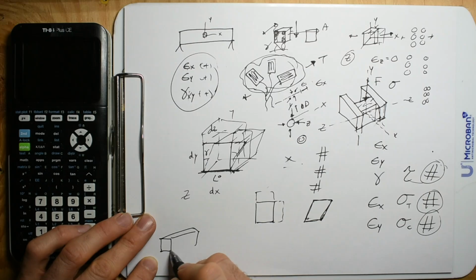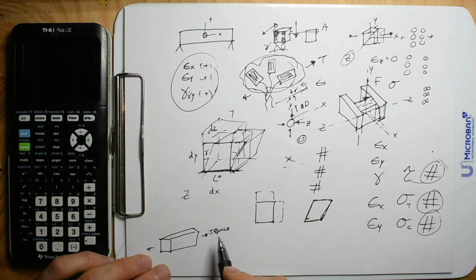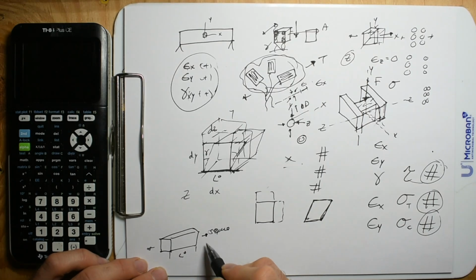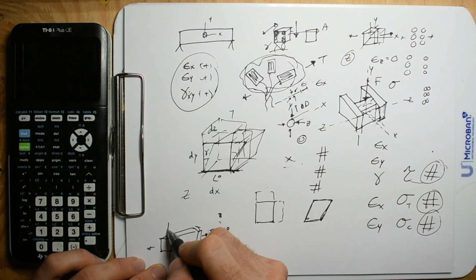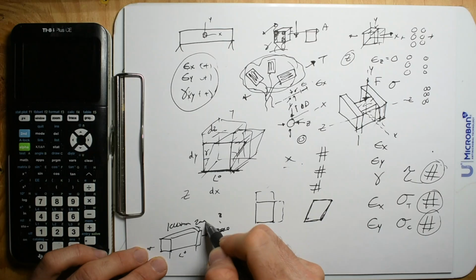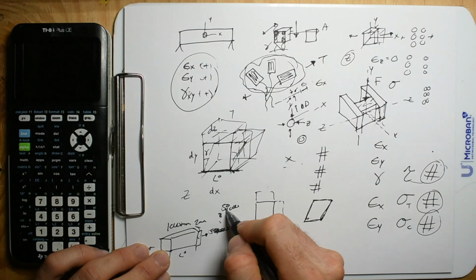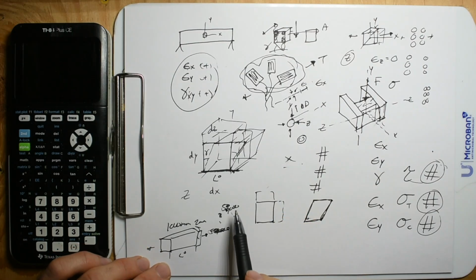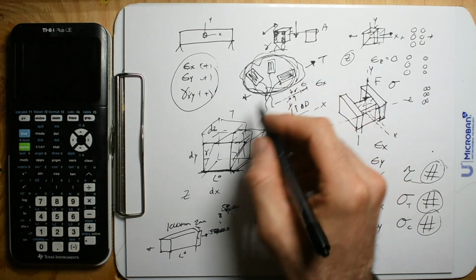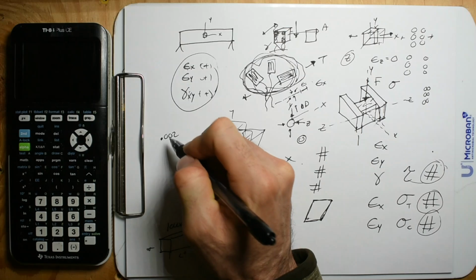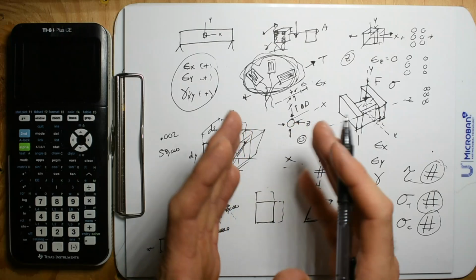If I have a 1-inch steel bar, I can know that I can put 58,000 pounds. That's one way. Or I can just measure its initial length and then measure its change in length. So let's say I don't know what load I'm putting on, but then I have 1,000 millimeters and I see 2 millimeters of lengthening. If I could accurately measure that, I'd be like, well, that's 58,000. And so I'm glad I said that, because that is the most overlooked thing about putting these gauges on. The second you put a gauge on, and if it's steel and you're reading .002, well, you're getting 58,000 psi in tension and compression in that zone.